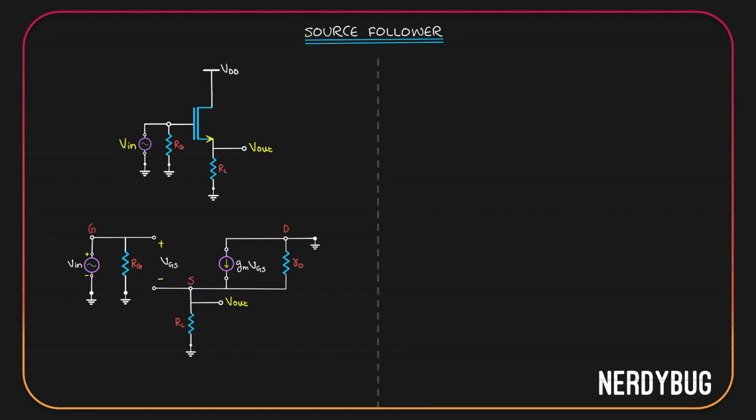Assume we have some resistance Rg at the gate. You can see that in the small signal model also. For that, the first thing we have to do is shut down all the independent sources, which is Vin over here. Now, since what we want is the input impedance, we have to apply a potential Vx over here and find its relation with Ix, the current that will flow like this. Vx by Ix will give us the input impedance.